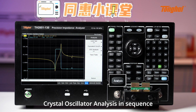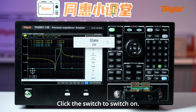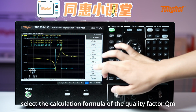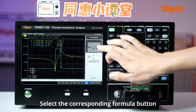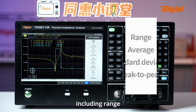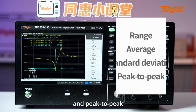Press Analysis, Crystal Oscillator Analysis in sequence. Click the switch to switch on. According to the actual situation, select the calculation formula of the quality factor Qm. Press Q calculation formula, select the corresponding formula button and click to set. Users can obtain statistical data on the curve, including range, average, standard deviation, and peak-to-peak for sorting.